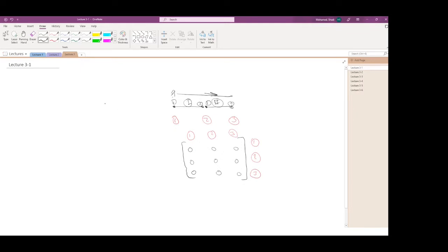So we write down the stiffness matrix for the first element. This is EA over L times plus 1, minus 1, minus 1, and plus 1. And this is for element number 1. And the same is true for element number 2. Whatever we have for EA, we put that in there. So it is 1, minus 1, minus 1, and 1. And this is node number 1, node number 2, 1 and 2. The same is correct here, 1 and 2, 1 and 2.